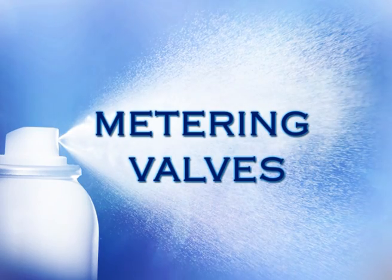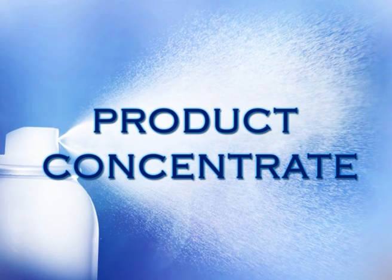Viscosity and the required rate of delivery play an important role in the selection of the inner diameter of the dip tube. Another valve type is metering valves. These valves are applicable to potent medication dispensing and operate on the principle of a chamber size that determines the amount of medication dispensed. Now another component of the aerosol is product concentrate. It consists of active ingredients or a mixture of active ingredients and other necessary agents like solvents, antioxidants and surfactants.